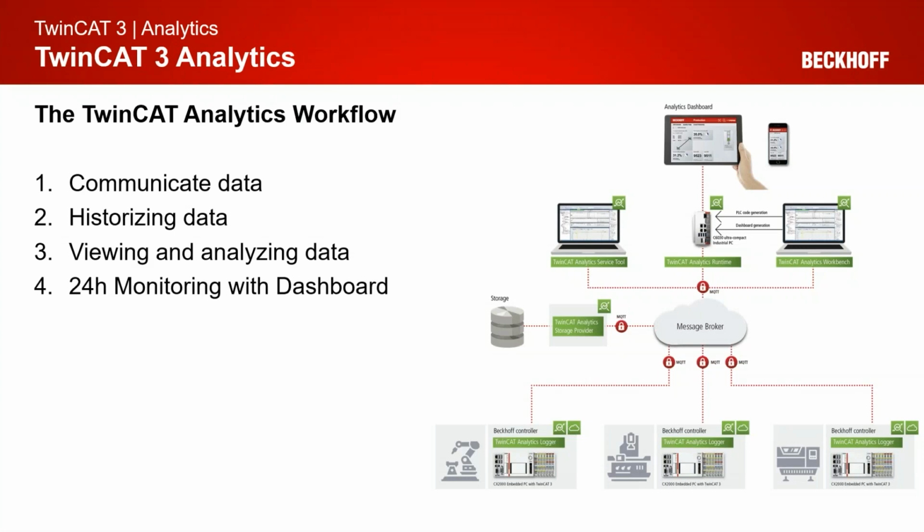The workflow, as you meanwhile know, is separated into 4 different steps. We were talking before about the data acquisition with the Analytics Logger and other tools, and the communication via the IoT communication protocol MQTT to the message broker. With the same protocol, we take the data and are able to store it by the TwinCAT Analytics Storage Provider. And then we can take live data from the machines or historical data from the storage provider in the Analytics Service Tool to make our first